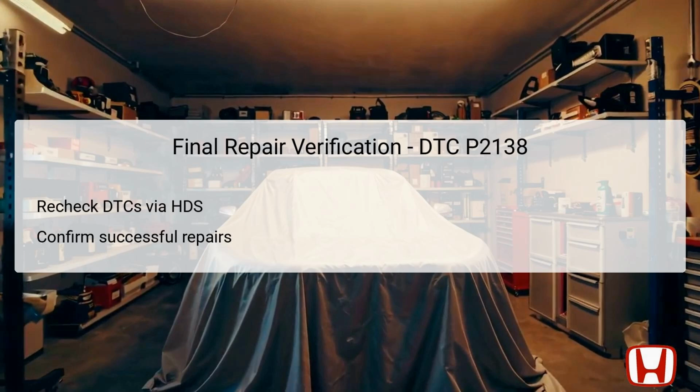The final step in the troubleshooting process involves conducting a verification of the repairs performed. After completing the necessary steps for diagnostics and resolving any identified issues, it's vital to recheck for any remaining Diagnostic Trouble Codes, DTCs, using the Honda Diagnostic System, HDS. This action will confirm whether the repairs successfully addressed the P2138 alert and that the vehicle system operates without further errors. If any lingering codes are present, it suggests that additional troubleshooting may be necessary.